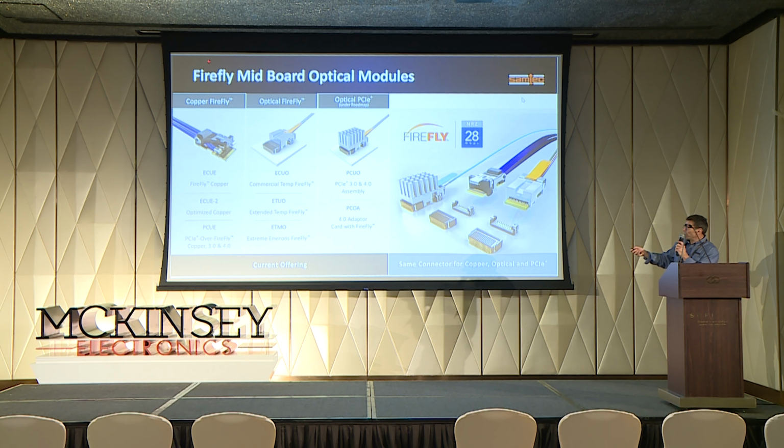And each of these modules, as you go through the series, from commercial temperature, wide temperature, to the military version, you can migrate through the series on the same pin mapping. You can then go up to the 25 gig series from the 12 gig series with a change of VCC, and all the lanes map OK. So there's a nice upgradability through the system, the Firefly, but essentially you're taking your optics from the front panel into the chip for density. Applications here are harsh environments. We're seeing military, aerospace, defense. We've got test equipment, EDA, and carriers.